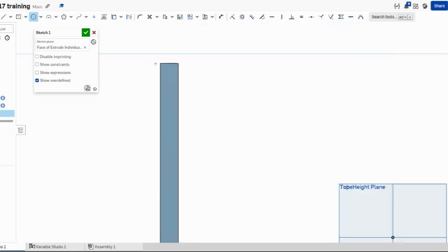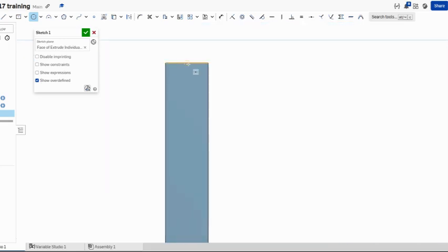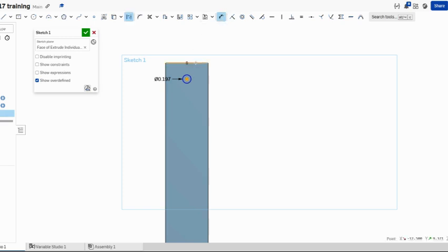And what I'm going to do here is find the center point. So I'm just moving my mouse around. There's the center of that, bring it down. And there's my circle. So that's the circle tool, letter C. When you click first, it sets the center. When you move your mouse and click again, it sets the outside area. So this is going to be 5 millimeters thick, and I'm going to dimension that. So click the center, click that line, and move it over here, and that's going to be 1/4 of an inch from the end.